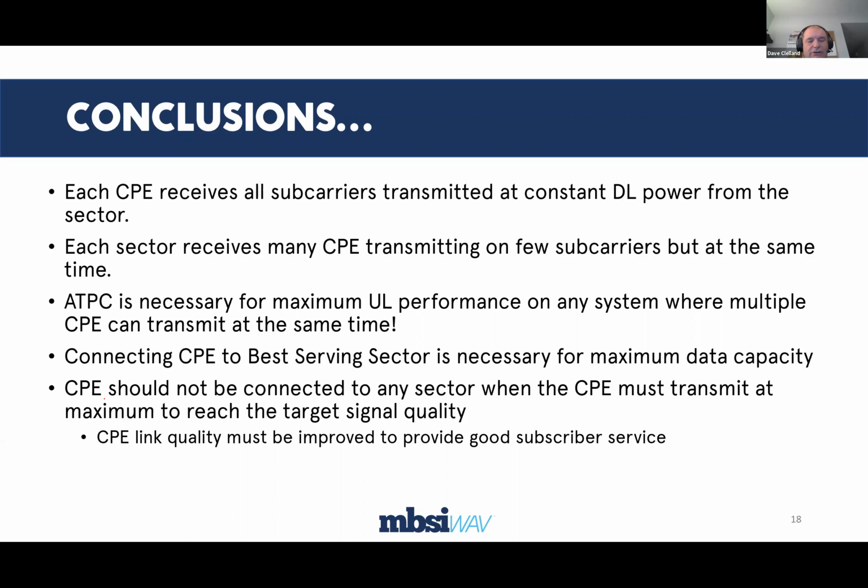So pick a threshold. In LTE, I tell people that the threshold should be negative 108 or negative 105 RSRP, the signal strength of an LTE resource block. In a 450 system, that number should probably be around minus 65 or minus 70 at the worst, but 65 or 60 is the right number.